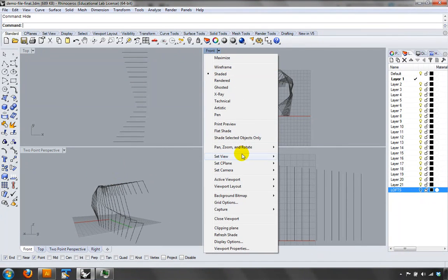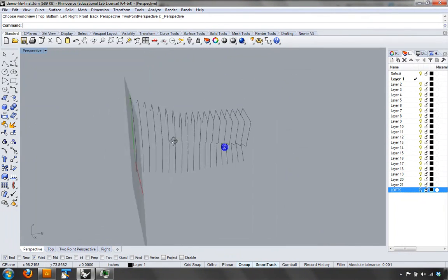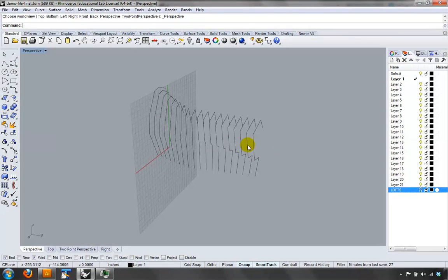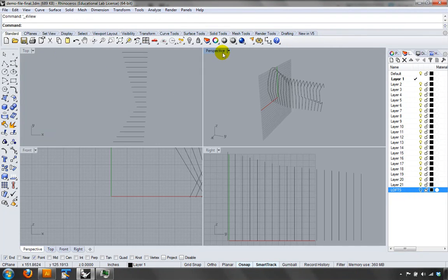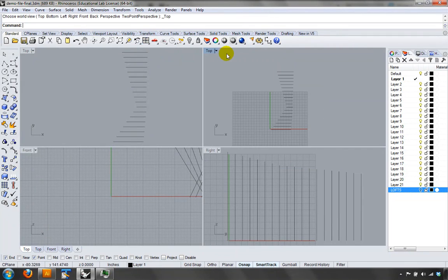So lofting is basically taking these cross sections and essentially trying to stretch a surface across them. If you ever get really confused with the viewports and you mess things up, just click on this Four Viewports button and that'll restore the default viewport configuration. It's a little tip.